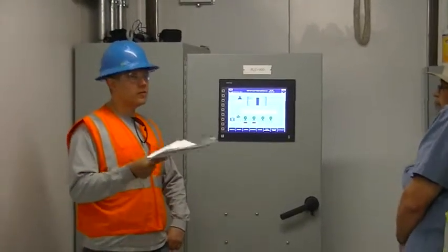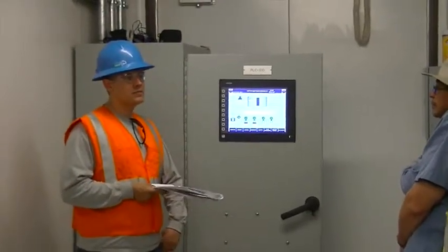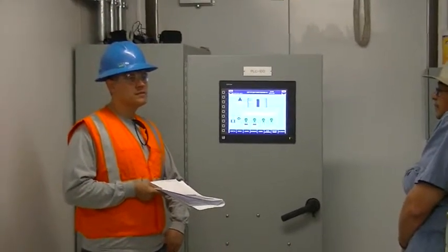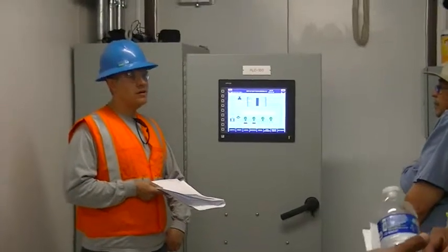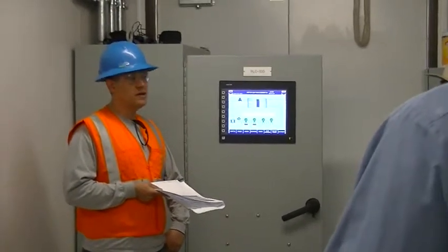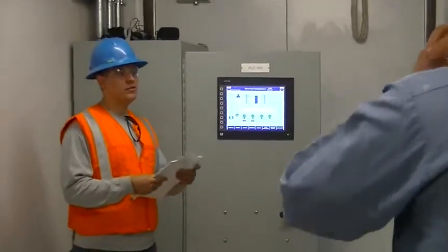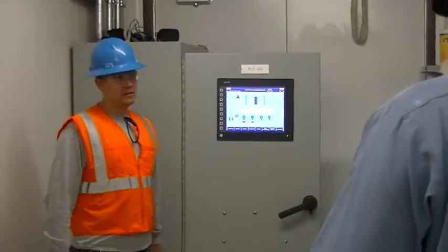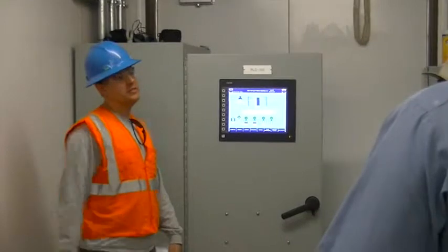They are gonna turn on and put a lot of pressure on your system. And they have high pressure switches out there for 75 PSI. Well, you can run them at a lower pressure too, though, right? Can't you, or no? Those are on or off. So the big ones are on or off. They're running full speed. So when those come on, that's why you'll be here when you kick them on, right? Yeah, manually, because they're gonna put a lot of pressure in your system.